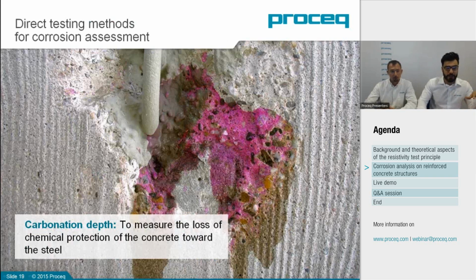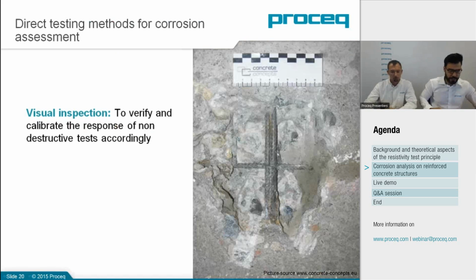But in the core of the concrete, the area you can see is purple, meaning almost no carbonation whatsoever, and that reflects on the health of this particular concrete structure. Lastly, we could go through a visual inspection, where we actually look and physically see whether we have problems, we have corrosion, and if that exists, then we need to take the appropriate measures to deal with it.